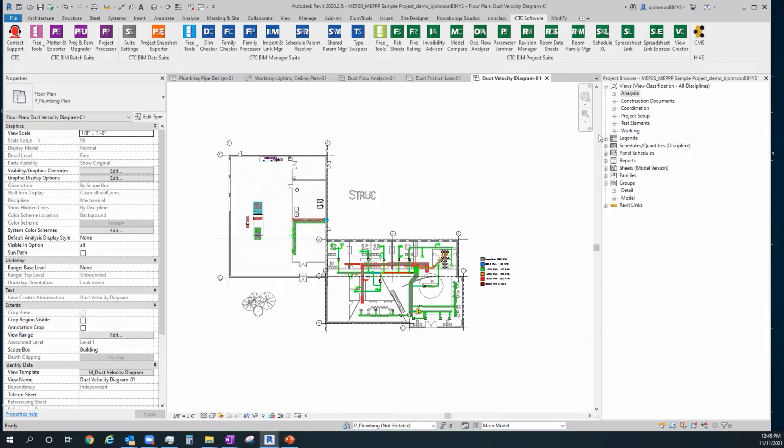So other things that we have here, I'm looking at my time again, still got 15 minutes. I think I'm good. Project Suite, tools people use all day, every day. View Creator for the setup of projects. Spreadsheet link literally gives you the ability to look into every Revit category in the entire project. Find that data that you actually want. So if it was, I want to look at all my air terminals and see how many of them still have 0 CFM, I can do that.